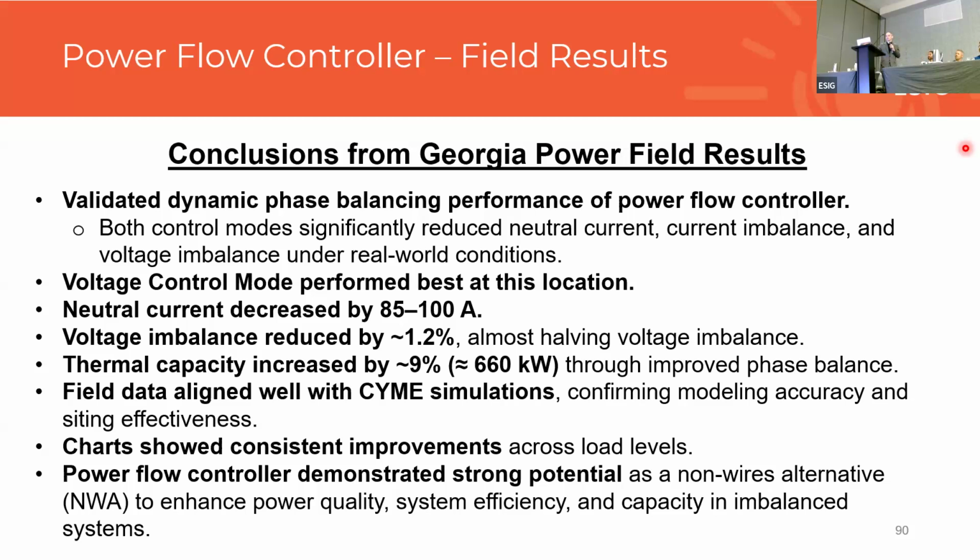So in this case, the power flow controller demonstrated strong potential for unlocking some of that capacity in the system that's otherwise tied up by there being imbalances in the way the system is being operated, because it is being held back by whatever your limiting condition is. Oftentimes, that is a single phase element on either voltage or thermal, whether it is high voltage, low voltage, or just pushing too many amps through one of your phases.